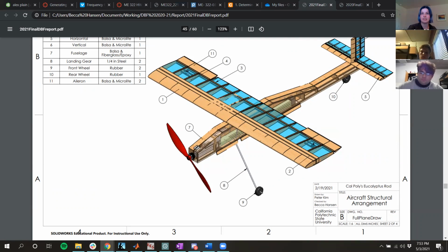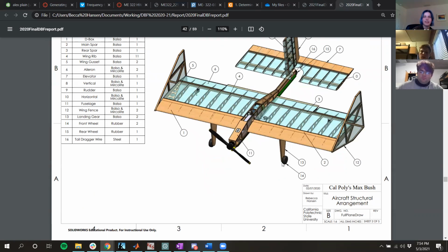That other guy was like fixed. Both of these would be fixed to the fuselage, but I think we should have removable composite gear. You said we're taking off from asphalt, right? Yeah. So wheel size doesn't really matter. We should probably get some squishy wheels, because you can stabilize without having suspension. You just get those rubber squishy wheels or foam squishy wheels. They're light. They won't pop. I think we should get some thicker wheels than we have in the past.